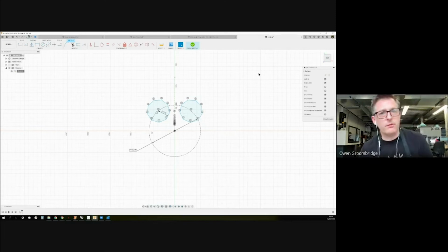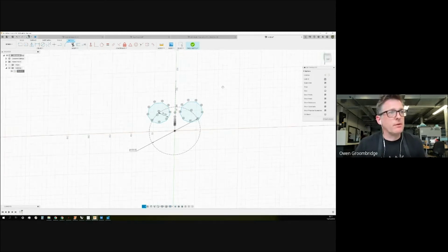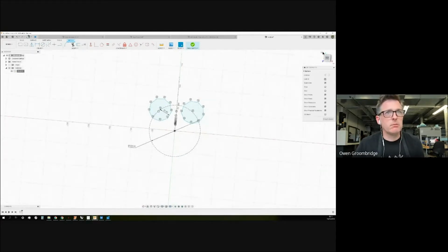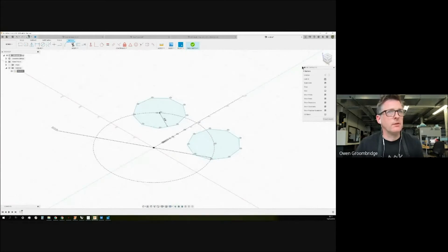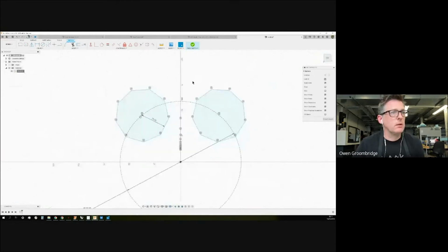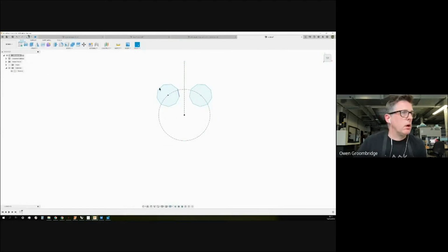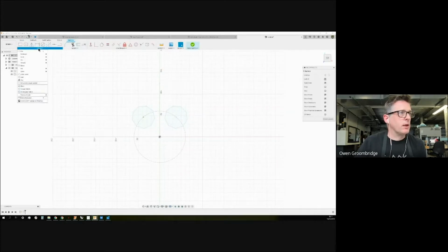Obviously, I showed you another way of copying in the previous demonstration about lines, and that is projection. As I said, you could project that onto another construction plane, or plane even. No worries at all, easy to do. For example, I might only want a certain aspect like that, and I'll just project it.